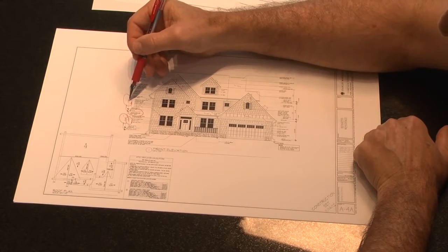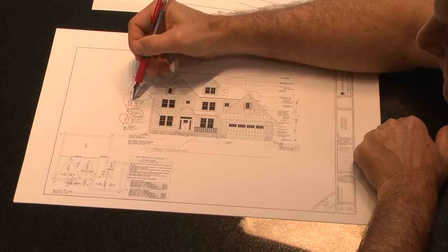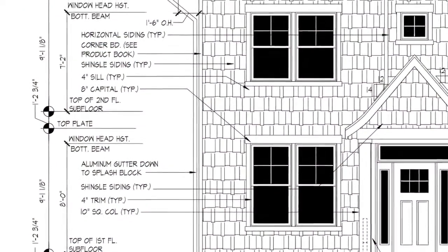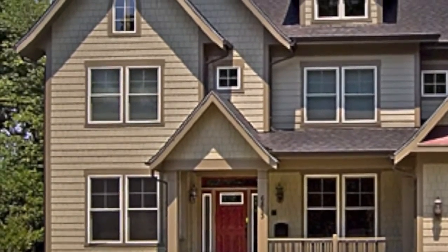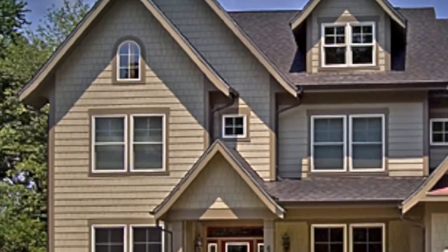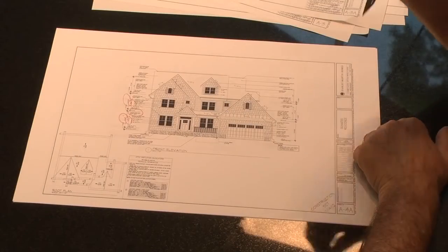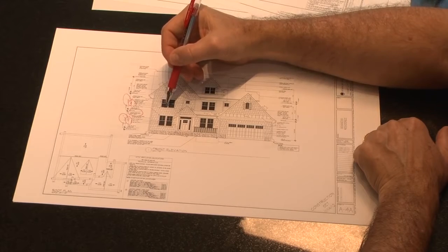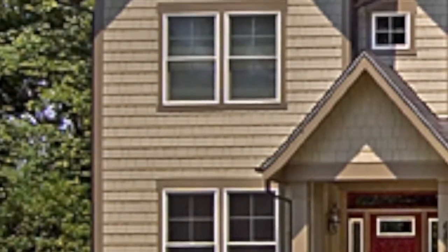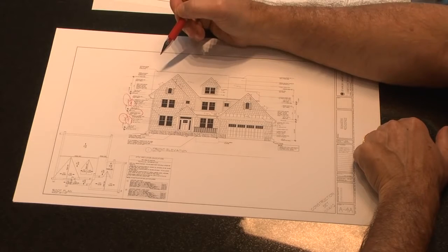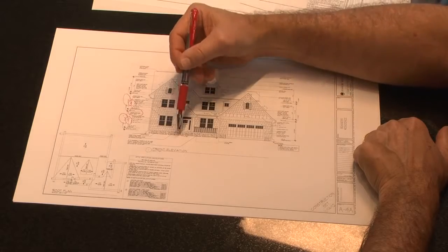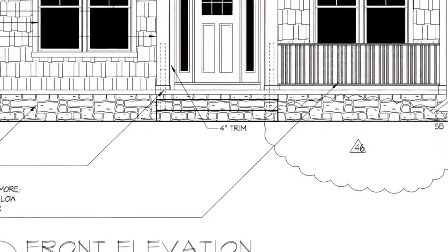It's actually 9 foot 1 1/8. And I just wrote over it, but this window head height was set at 7.2. The reason the window head height on the second floor is set a little lower is that the windows on the second floor are 3050, not 3060. Also, on the second floor, we need the windows to be at least 2 feet above the floor. Otherwise, there's a safety concern and we have to do some special detailing, whether it's rails or whatnot, so that it meets code.